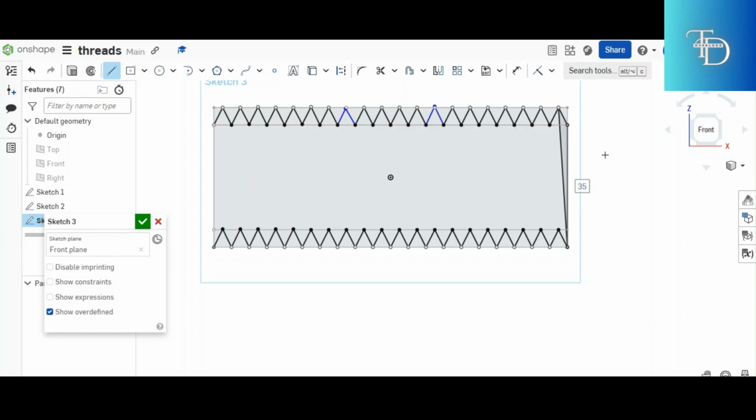The only thing that is left now, you follow your creations. This line right there on the far end, it was joining with the opposite far end. And then the inner part, it joins with what? With the opposite inner part. You have a far end, it joins with what? With another far end on the opposite side. And then from the pitch line to pitch line, far end to far end, pitch line to pitch line. Keep doing that until you get done with the thread.